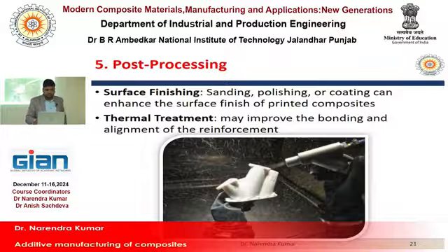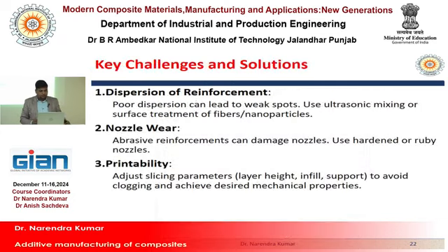I'm not going to cover this in detail because of the time. Quickly I will finish. Okay, so key challenges: dispersion of the reinforcement is a very important parameter. Poor dispersion can lead to weak spots or defects within the developed composite, right? It may create holes, right? It may reduce the strength of the material, flexibility, and elongation at break may decrease.